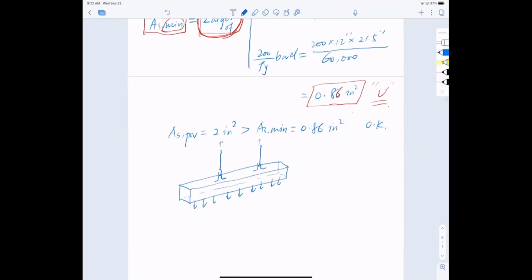So this is equivalent to a simply supported beam, with the lifting spots as supports, and you are exerting a uniformly distributed self-weight on it to create a bending moment. Naturally, this region in the middle is the so-called constant moment zone.